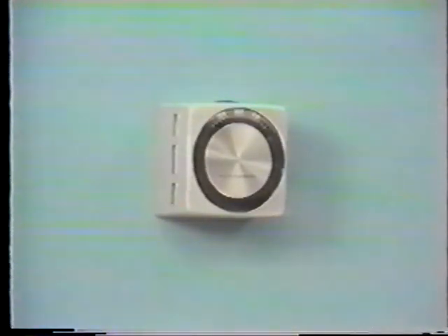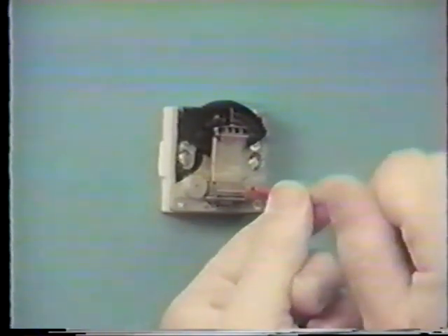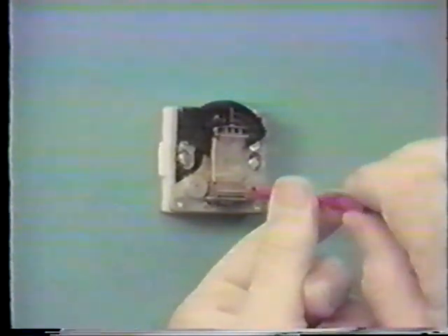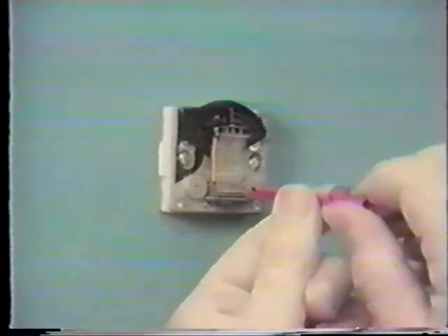The 2230-018 humidistat is factory set for a 10% throttling range, reverse action, and calibrated for 9 PSIG branch at set point. However, the device may be changed to direct acting if required by the application. To change the action of the humidistat from the factory set reverse action to direct acting, simply rotate the switching screw 10 complete turns counterclockwise. This change should not affect the calibration or throttling range setting. No further adjustments should be necessary.